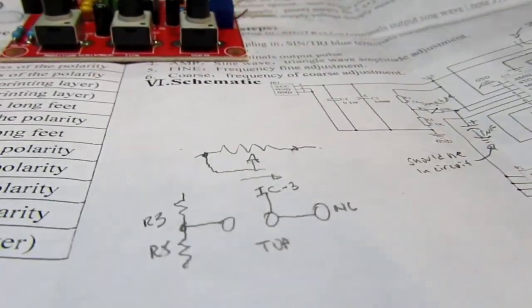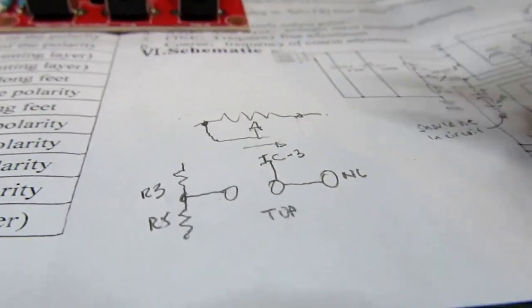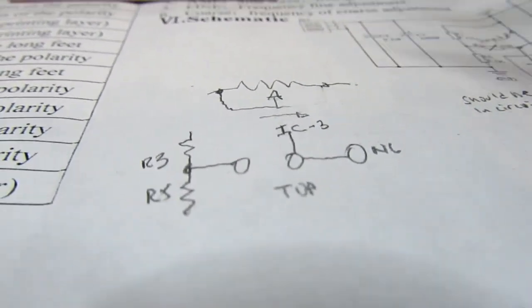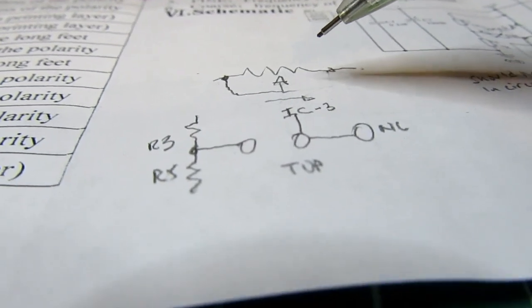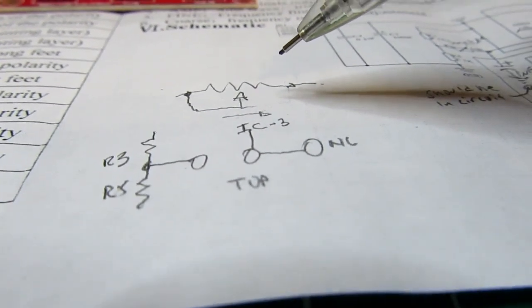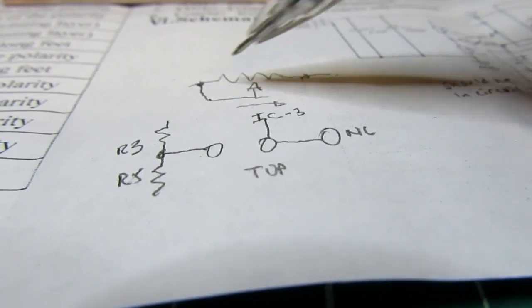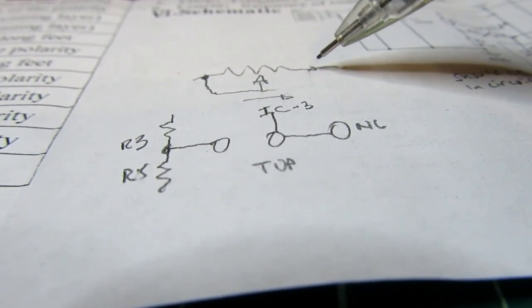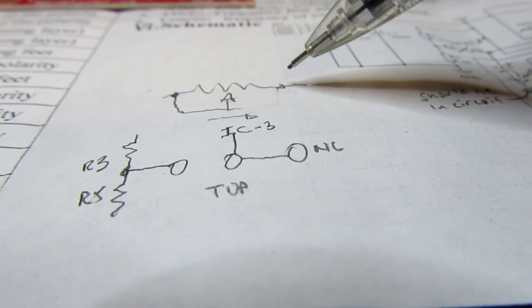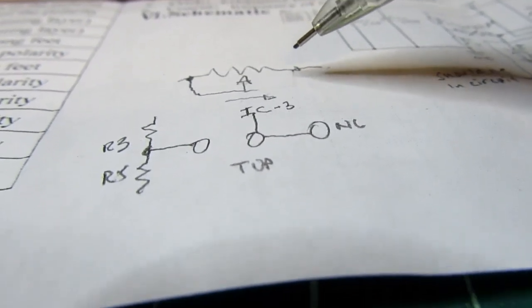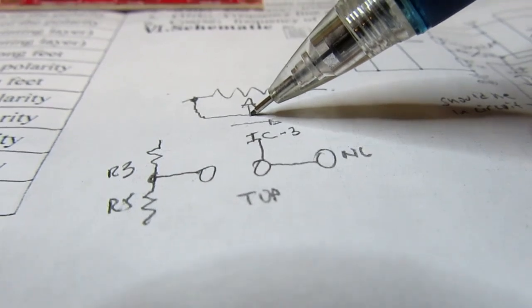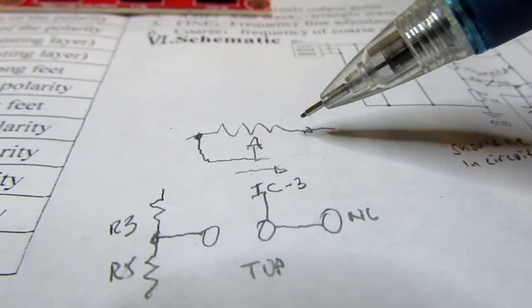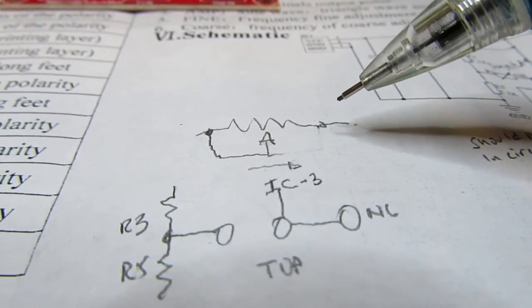Best practice would indicate when you're using a potentiometer as a rheostat, or just a simple variable resistor instead of as a voltage divider, that you connect the wiper to one end or the other of the element instead of leaving one end of the element hanging. It's not ideal to leave one element hanging. And if you did that, then all you'd have to do is move the jumper or whatever foil or jumper there is from the wiper to one end or the other of the element, and you'd be good.